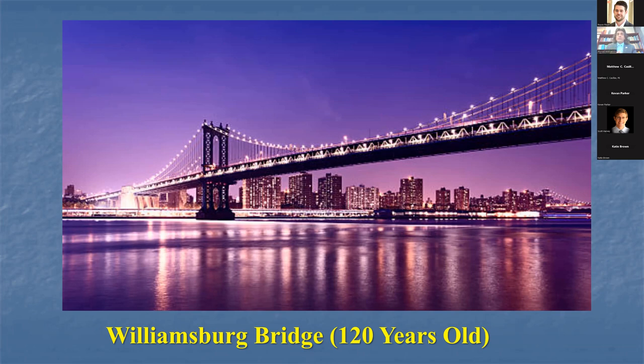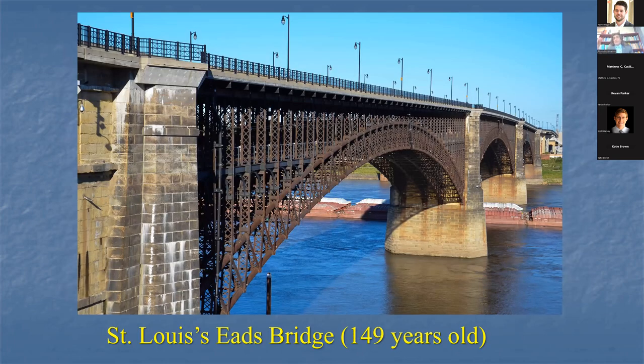So that's another lesson. One of the reasons, other than the maintenance and the rehab, is the very high safety factor that went into the design of some of these bridges, like the Williamsburg Bridge, which had a safety factor of 5 for the cables. Over time it decreased to, let's say, 2.5 or 3, but it still is good enough to meet the current criteria. Another bridge, for example, that has lasted a very long time.